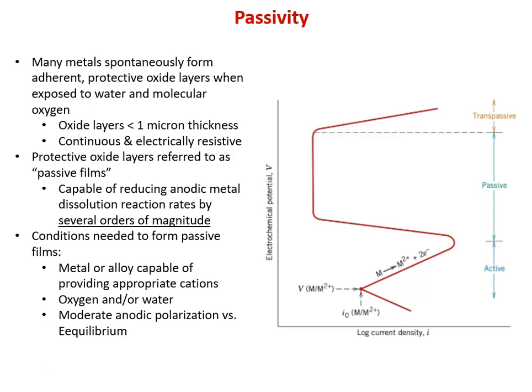It is literally the spontaneous formation of a tight, thin, adherent oxide or oxyhydroxide layer, usually mixed metal, on a metal surface on exposure to a corrosive environment. Typically these are environments that, not surprisingly, have quite a bit of dissolved oxygen. Oxidizing environments, reducing environments make this tough, and that's why quite often you have to go to fairly elaborate, exotic, and expensive alloys when you have to protect them in reducing environments.